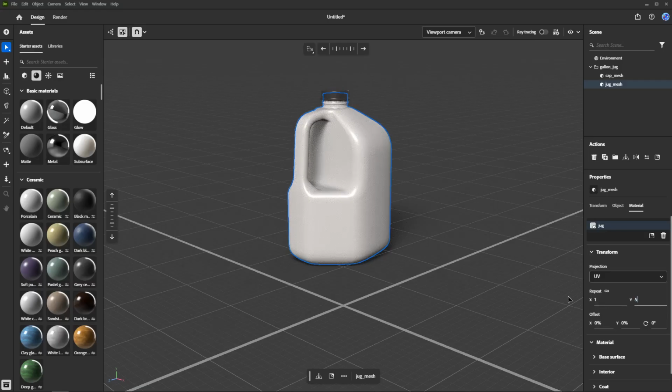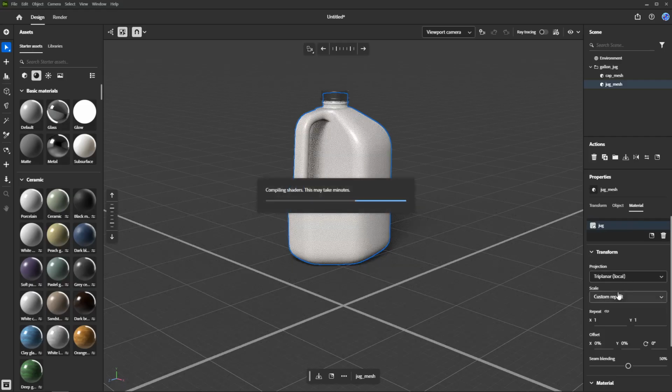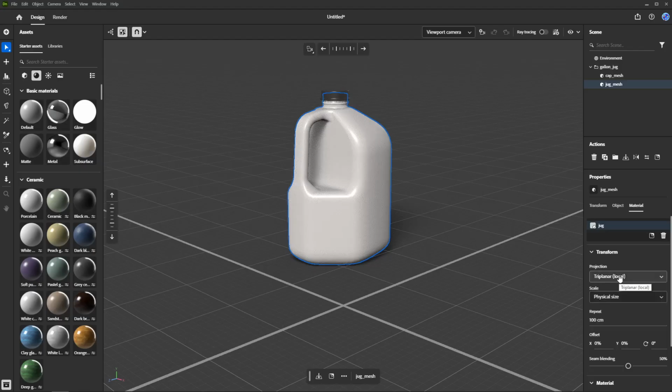Experiencing visible seams or mismatched edges? A seamless texture, a texture whose edges match up smoothly, can do wonders. Additionally, considering the triplanar projection mode under Material Projections can help mitigate visible UV seams, particularly useful for objects that aren't UV unwrapped. As you make these changes, remember to rotate around in the viewport to check that your tiling looks consistent from various angles, ensuring a quality perspective from all views.